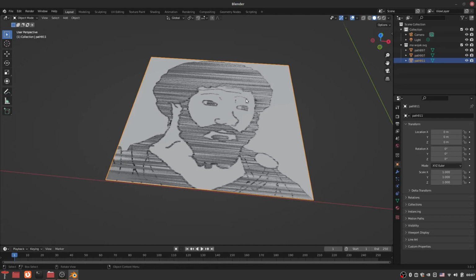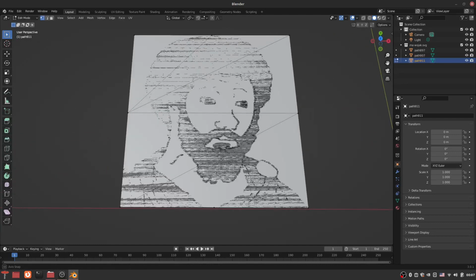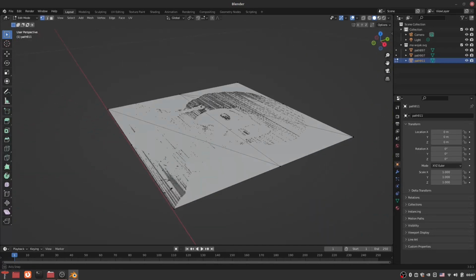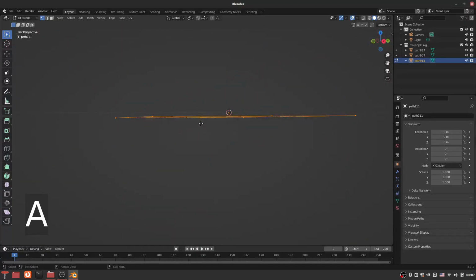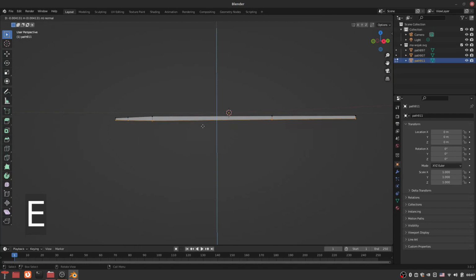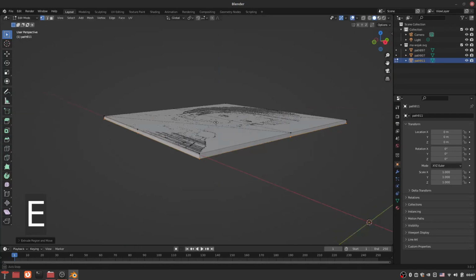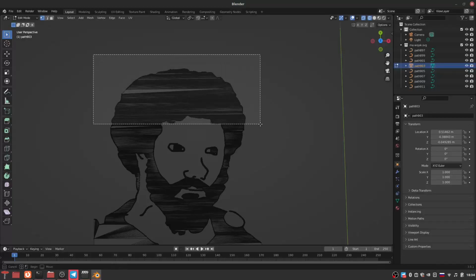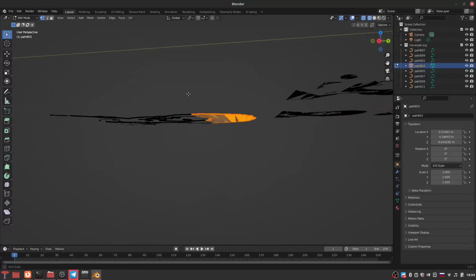Then select a new mesh and press Tab. It'll take you from the composition mode, where you arrange multiple objects, to the selected object editing mode. Here press A to select all vertices and E to extrude them. Extrusion creates a copy of selected nodes and relations between them, connects corresponding nodes, and by default moves it in a direction perpendicular to the average plane of selection.